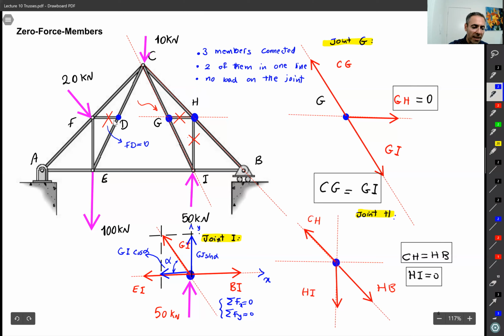Then get rid of DF. Oh, you may say, what about F? You say, okay, just look at one joint, one point. If one point has these 3 conditions, you are good to go. Remove DF. What about FE? So imagine that DF is invisible, it's not there.